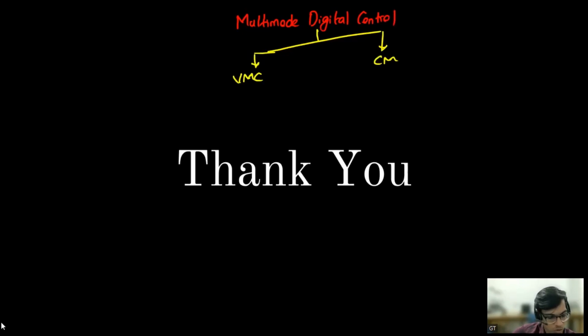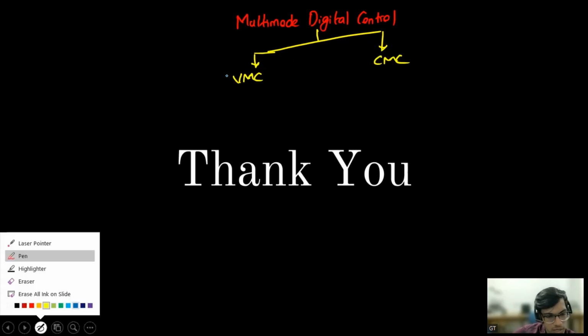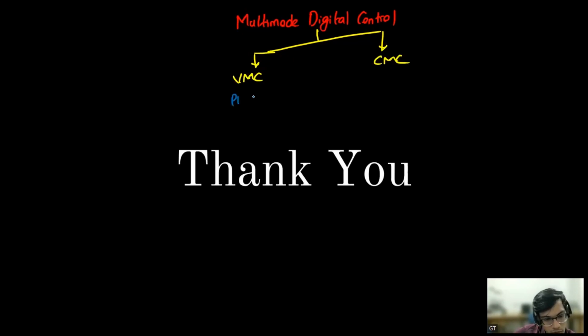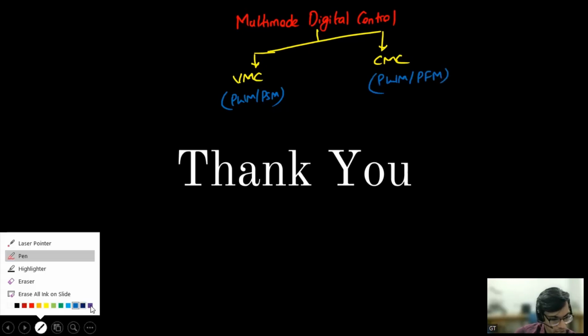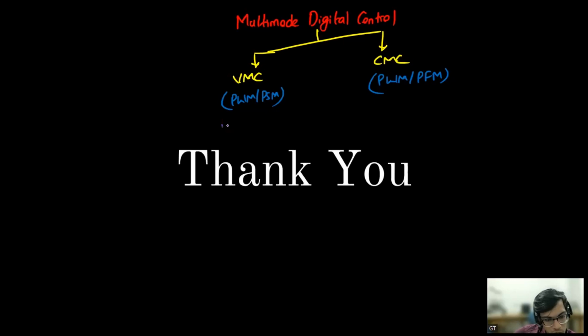In the voltage mode control, we have discussed PWM PSM, and in the current mode control, we have discussed PWM PFM. In PWM PSM, it is digital voltage mode control plus digital pulse skipping modulation. Here it is peak current mode control plus adaptive on time.